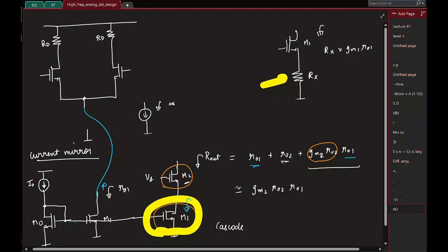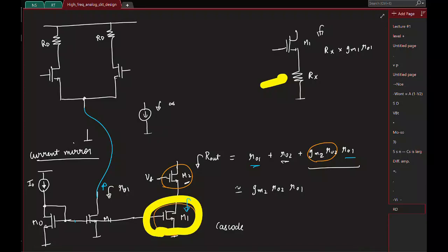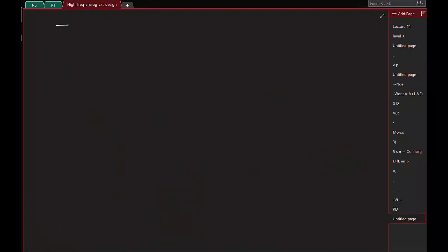Is that okay? So what is the gate of the M2? Not there. Here. The cascode. That is connected to some bias voltage. Incrementally it should be short. It's a common gate, so incrementally the gate should be short, but you will have to bias it so that it remains in saturation. Great. So now you kind of know how to implement everything in this diffamp.